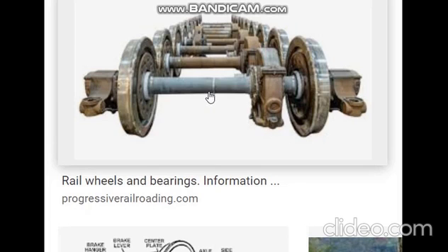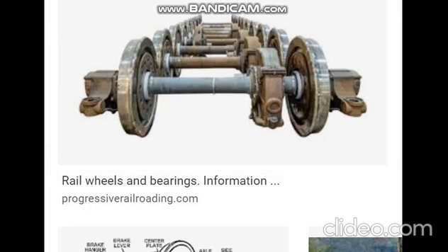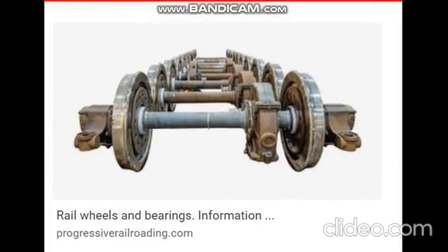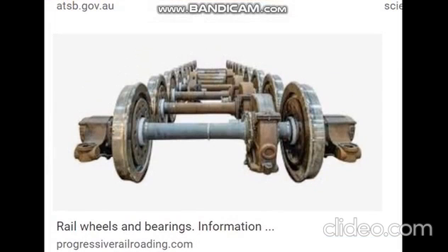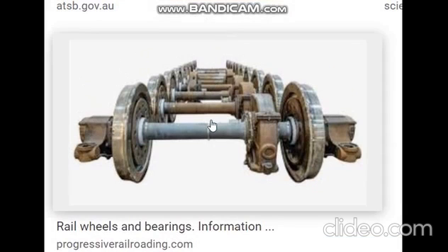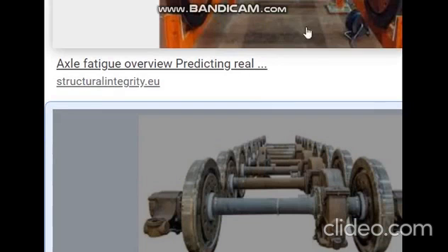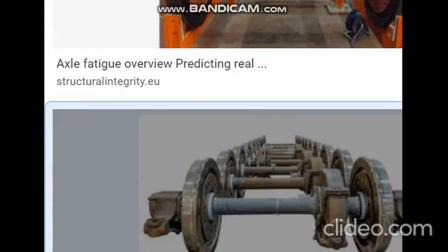Under that repeated loading, I showed you that chart. In that repeated loading, if there is a crack somewhere in these machine components, it slowly propagates. I showed you how catastrophic a failure it makes, and it will break into two. Such a failure is called fatigue failure.